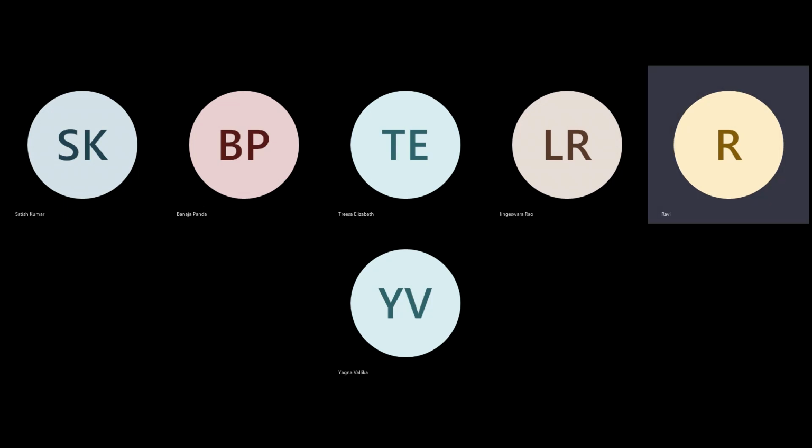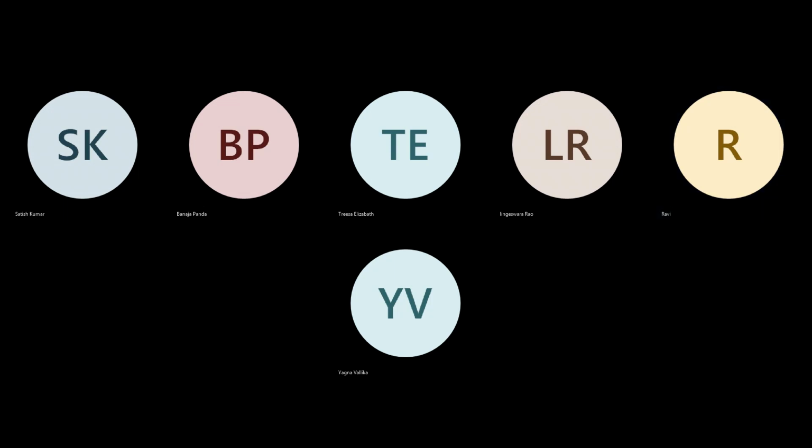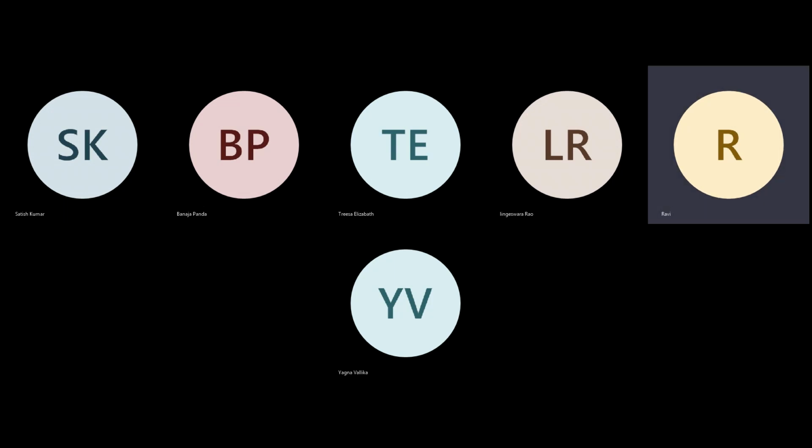The idea of double patterning, triple patterning is that the first pattern is laid, then after a certain cool period the second pattern is laid. Only then will you be able to create that minute pitch. Otherwise, in a single layer, if you try to merge, it will create gaps, shorts, etc. That is the idea of double and triple patterning. And if you have so many grids coming in, then there's a real problem.